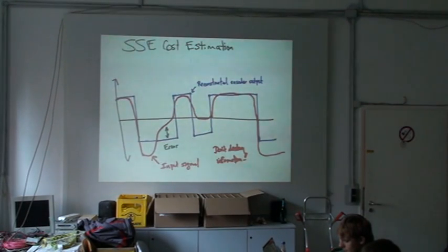So then we get back here. What we're really doing is the cost estimates in the cost estimation phase of the Viterbi algorithm. We're not comparing bits to bits. We're comparing hypothesized output bits against an input signal which is not binary. That means that when the signal was in some indeterminate state, we're not going to force the Viterbi algorithm to make a bad decision.